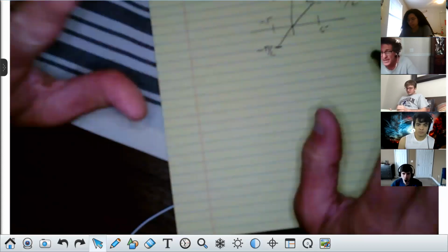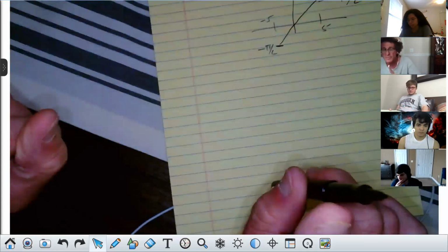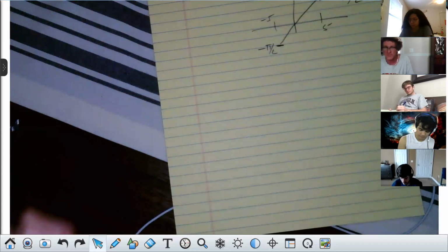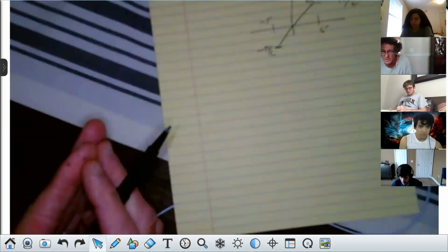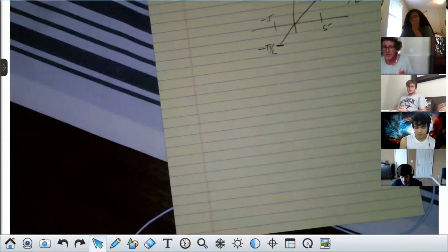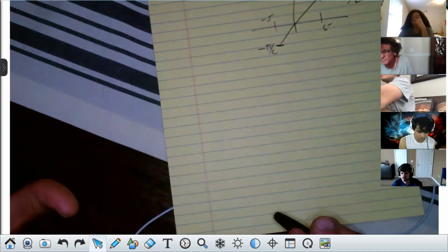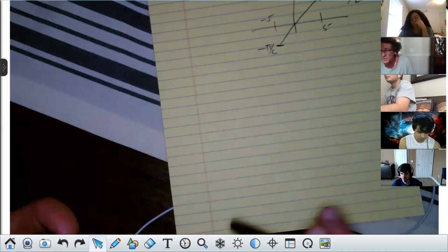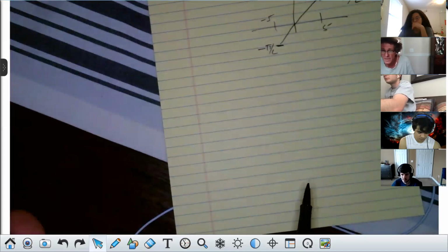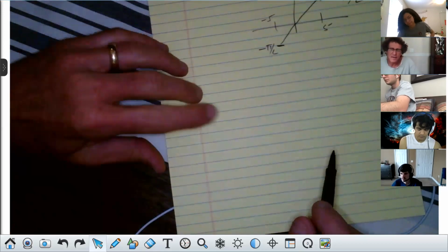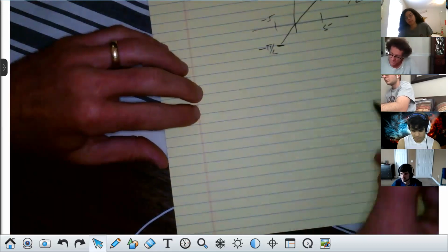Now, if it was a finite duration, something non-periodic, then convolution would be acceptable. But I'd really do it in the transform domain first. I'd take the transform of the first function, the transform of the second function, then multiply them, and then take the inverse transform. Are you with me with this? I'd probably do it in the S domain, to be frank about it, unless they had negative values, then you couldn't. You'd have to work in omega.